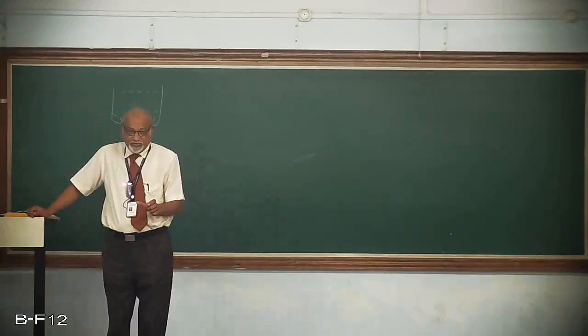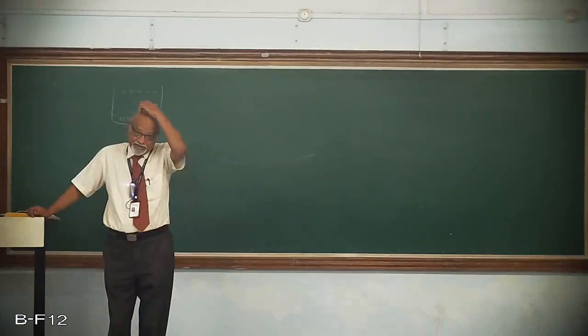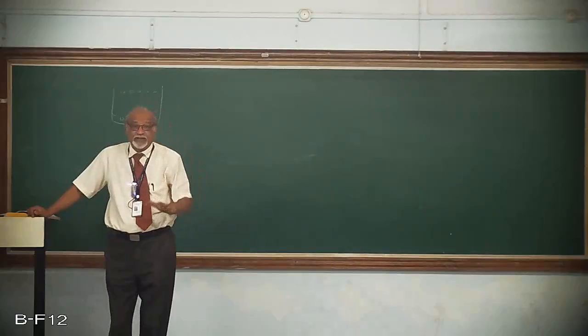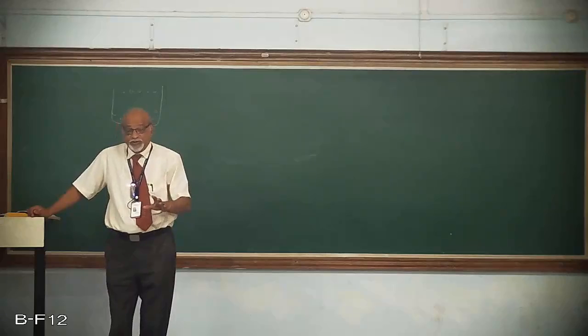So its length should be within this much. That is what we are bothered about. It should not be more than 10.5 mm and not less than 9.5 mm. 9.6 mm, yes, okay. Up to 10.4 mm, okay. Up to 10.5 mm, okay. But the moment it is more than that, no.